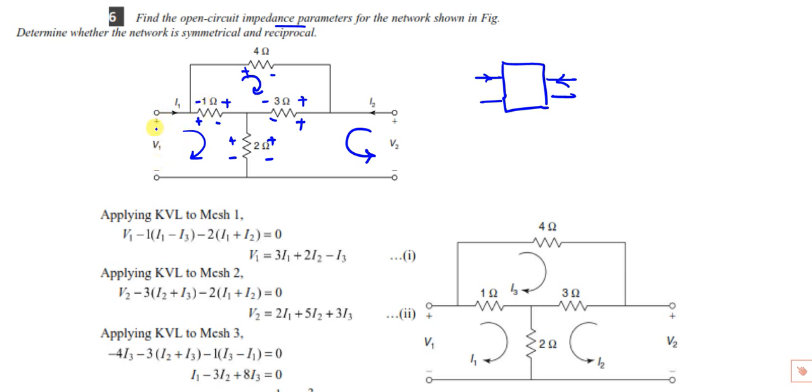Now apply the KVL formula. Minus 2 plus, you can write minus here. I told you, different authors use different notation. In this book they used minus 2 plus as positive. In the other problems I explained, I write whichever comes first. If you bring it all throughout, you multiply by negative. This full equation, if you multiply by negative, this minus becomes plus. Don't multiply here, only this, because this is a term, this is a net current.